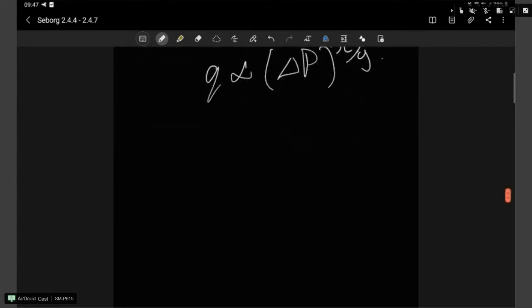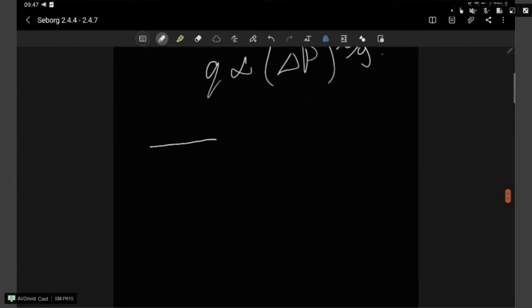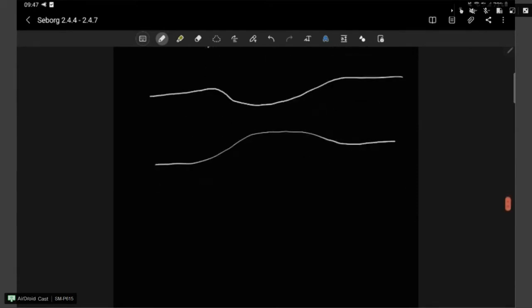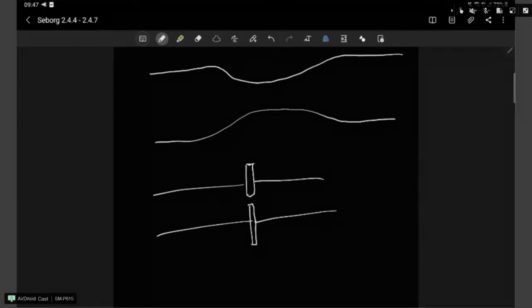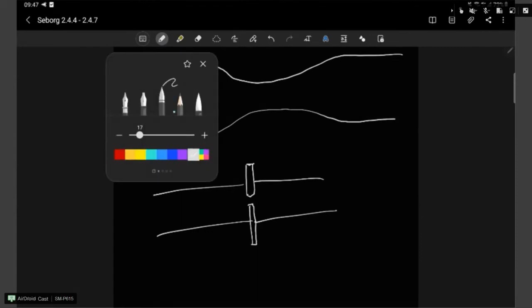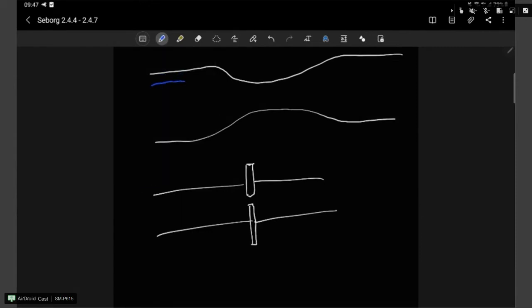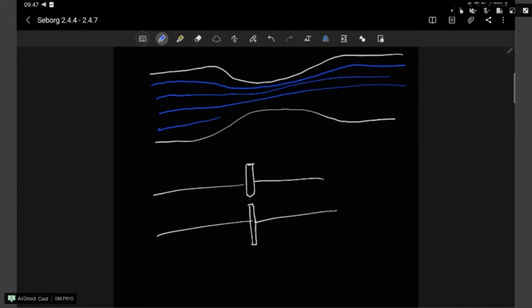So it's basically, and I think you all know kind of like the Venturi effect, if we have something like that, some form of restriction, which we can assume to be an orifice plate as well. In such a system like this, we obviously find ourselves with well-developed streamlines in this, and this is why they refer to a valve as possibly being like an orifice plate, because over an orifice plate this is true, or to some extent at least.